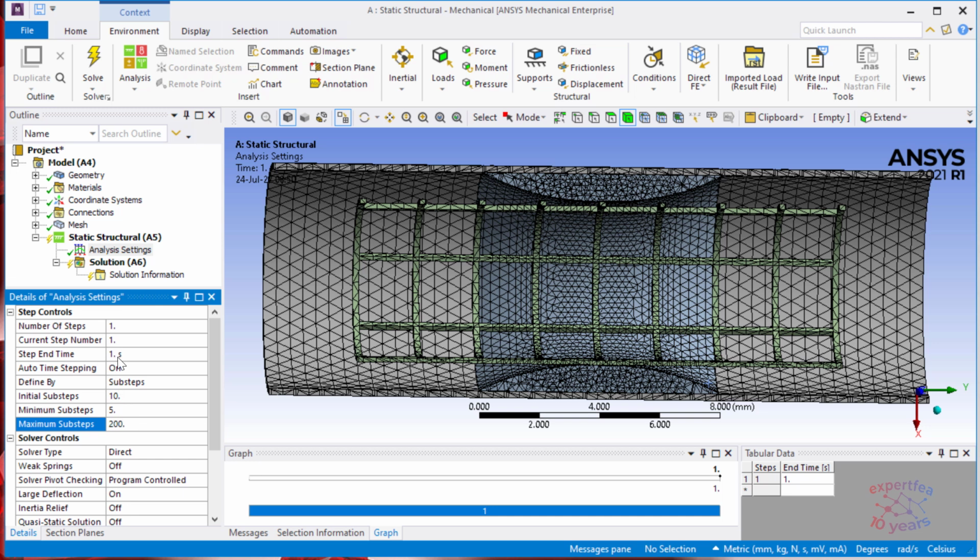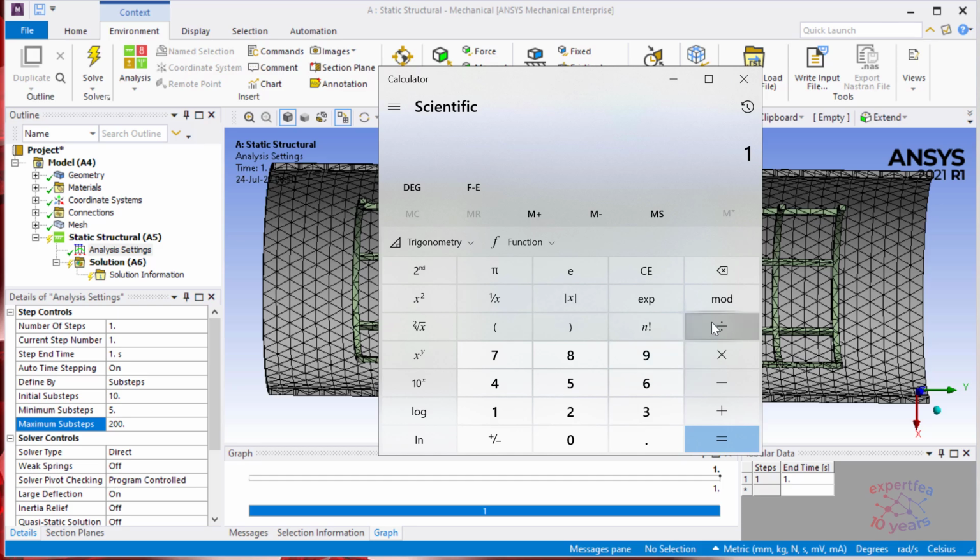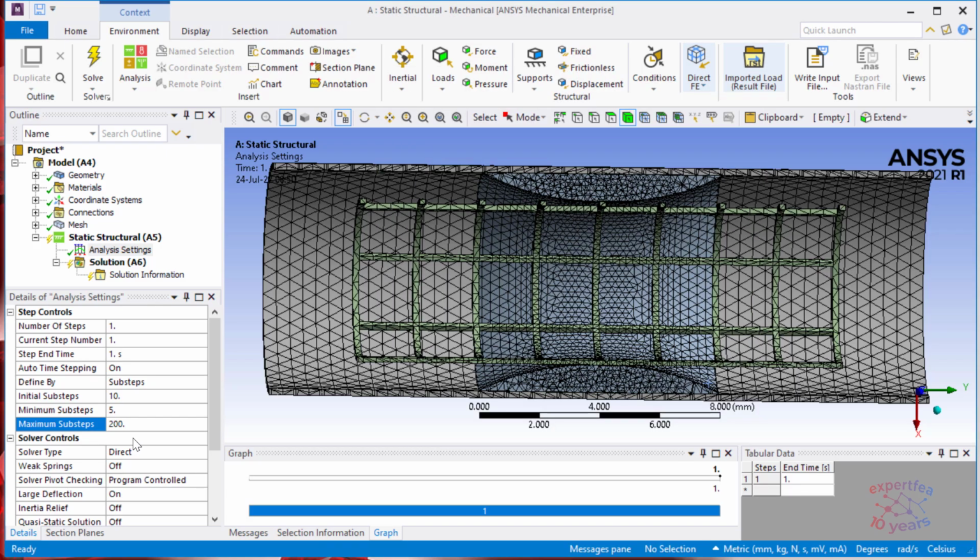And you can extrapolate that if there were a physical time of 1 second for the duration of the simulation, then divided by 10 we have 0.1 as a time step, then 0.2, then 1 divided by 200, we have a minimum time step of 0.005 seconds if we are judging from a time perspective.